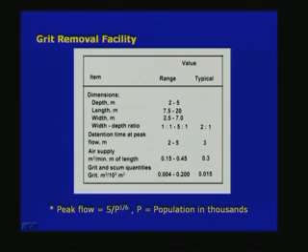the various parameters that we can see. Design parameters for the aerated grit chambers. Again I am taking the source from Metcalf and Eddy, and we have these dimensions. Depth is 2 to 5 meters, that is the range for the depth of the grit chamber.